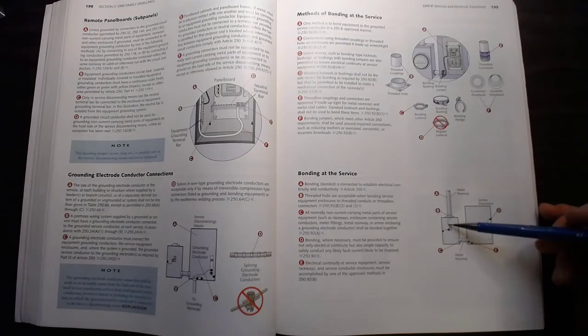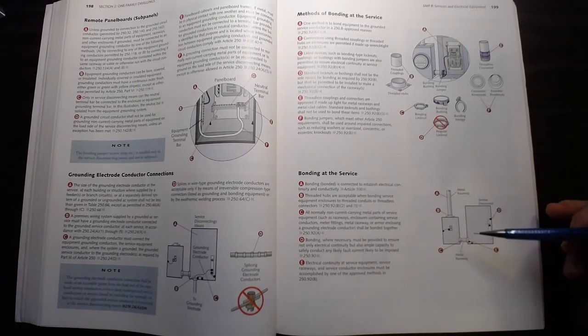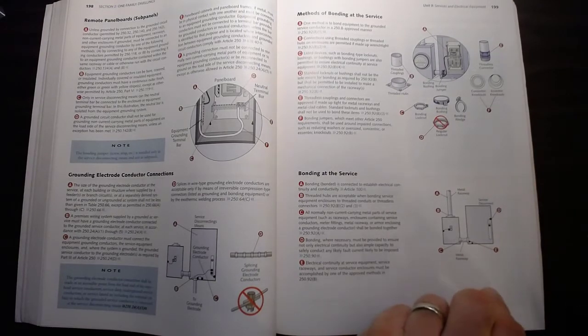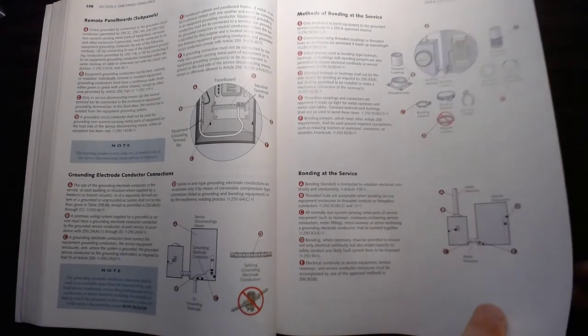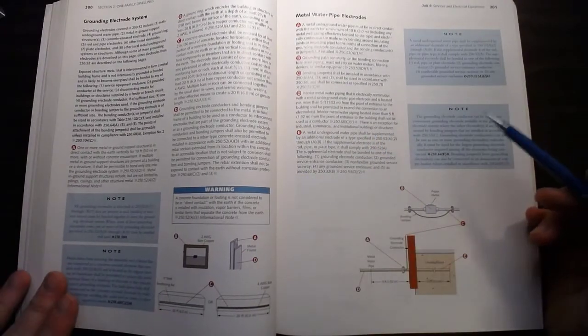You can use the metal conduit as the grounding path, but I never did that, because the conduit can separate, the fittings can break, and then you lose your ground path. It's one extra wire to pull in. Don't fight it, just put it in, because it will give you the best path back to the service for tripping the breaker. So all conductive parts need to be bonded to make sure that it's all connected together.